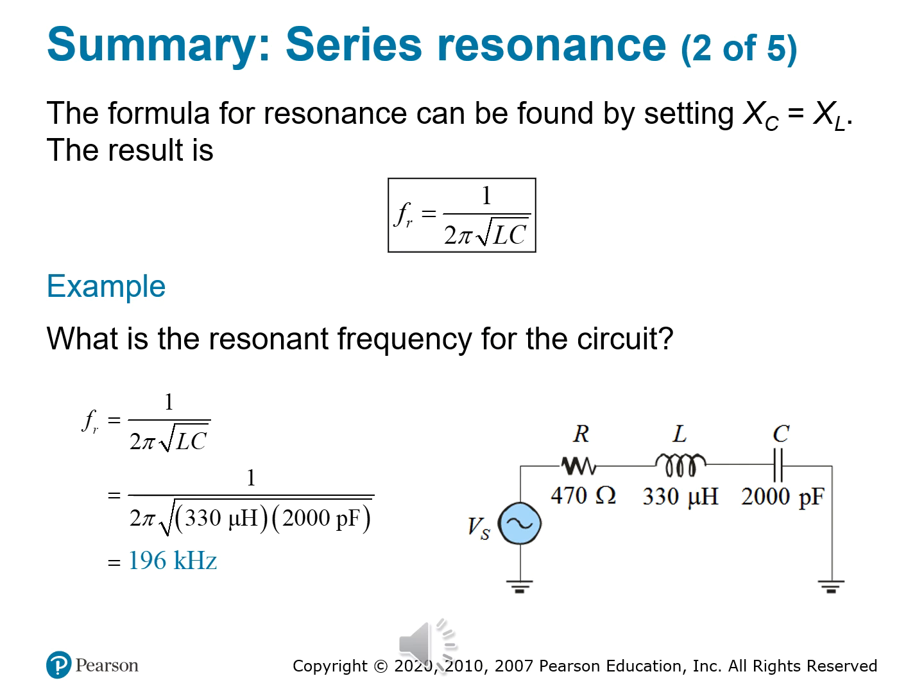There is a way to derive this if you don't believe me. Just go ahead and set X_C equal to X_L. Plug in their formulas, and you eventually will get, if you derive it, this formula for resonant frequency: 1 divided by 2 times pi times the square root of LC, right? Again, simple, elegant. And what this formula tells you is the frequency at which the reactances cancel each other out, leaving only resistance. So just plug in your inductance, L, and your capacitance, C. Again, no Ouija board needed, maybe an oracle or two, and voila.